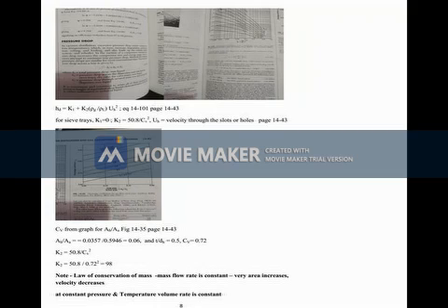Now you construct the graph between the operating line and equilibrium line. Actually, in your previous example you would have done it. It's exactly one and the same. There is no change, but you do it once more so that you will be thorough with the procedure. Mind that this minimum solvent calculation is used only if the amount of solvent is not given. If the amount of solvent is given, then you need not do this exercise. L is known, so LS is known, GS is known.